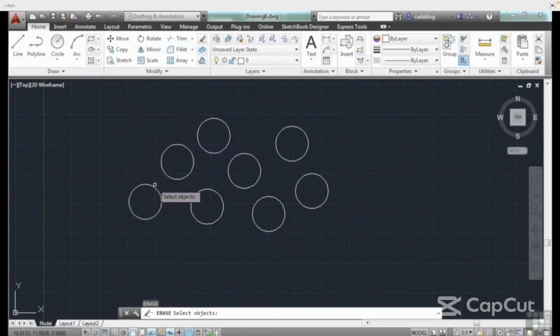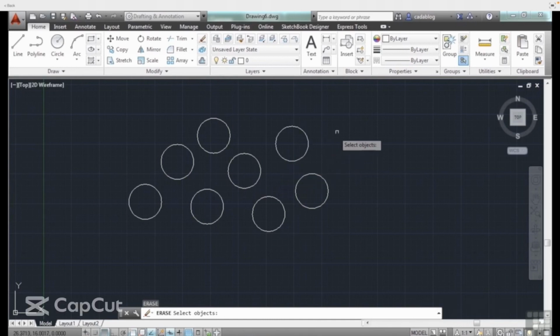As you hover your mouse over an object to be selected, AutoCAD will highlight it, saying, hey, this is what you're picking. That's how you know that you're picking the right object or not. One thing you can do is called a window. I pick a point here just in space, and you can see I have 2 different colored windows. This is your window selection method, and there are 2 methods available to us.